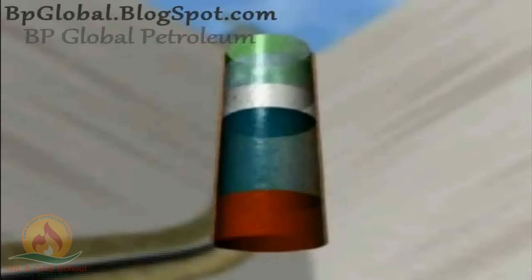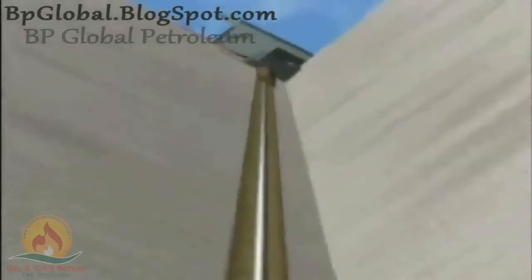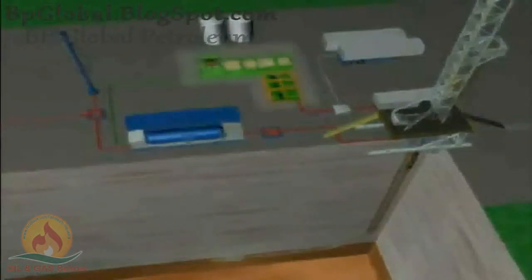In what follows, the commonly used two-phase flow system is shown as an example to illustrate the technical differences between underbalanced and conventional overbalanced drilling. A two-phase flow system setup consists of the following elements. The light drilling fluid is stored in the rig's mud tank system and is pumped to the well by the rig fluid pumps.